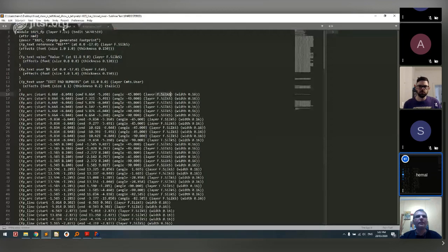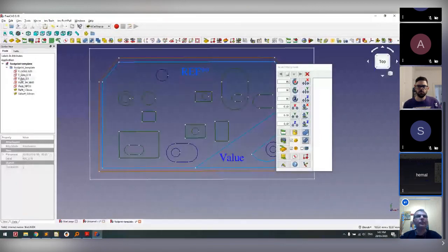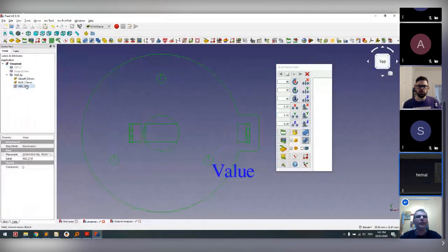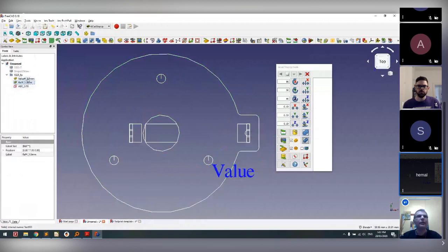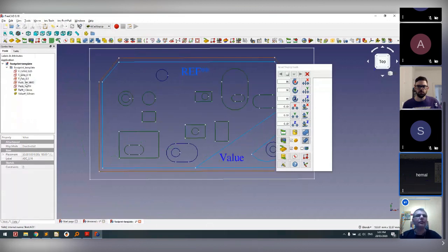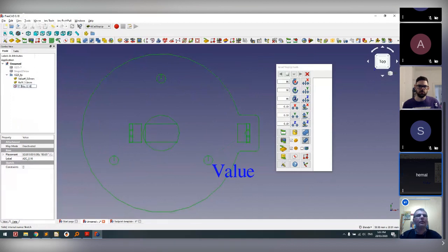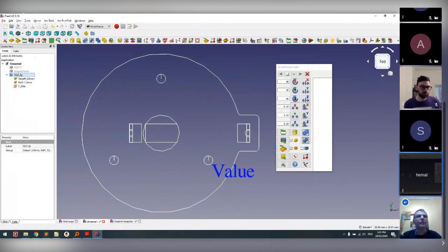this text was a bit different. So this name comes from here. What happens if you just export as F_Silk, but without the width information? So instead of F_Silk_0.16, if you just do F_Silk, does that work? Let's try. I'm thinking it should default to some default value.